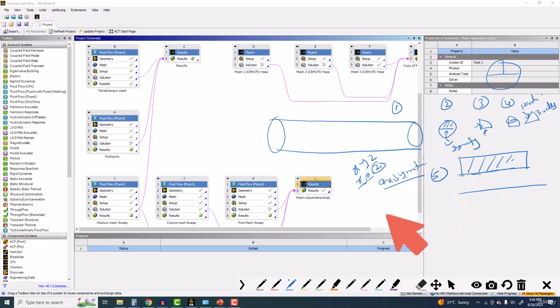What we are doing here is assuming something we already discussed in the theory part: there is no change of the fluid velocity along the axial direction, that is, du, the x velocity, with respect to y. This is the condition when the flow is fully developed.